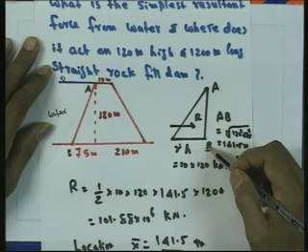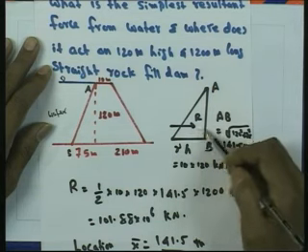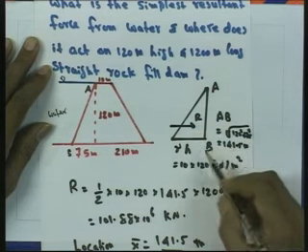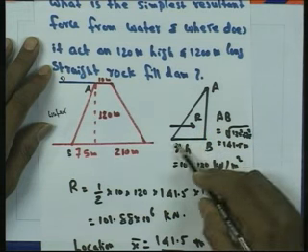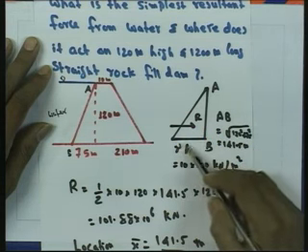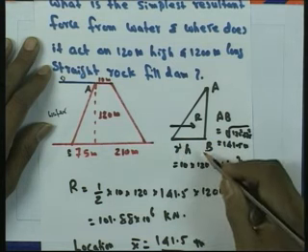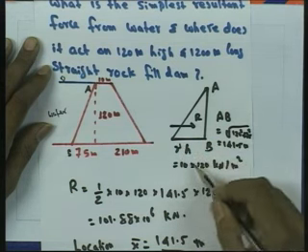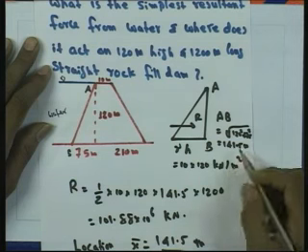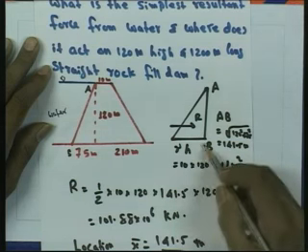On this AB the resultant force R will be acting like this, and at the base the pressure will be gamma into H. If you take gamma as 10 kilonewton per meter cube, that will be 10 into 120 kilonewton per meter square at the base.